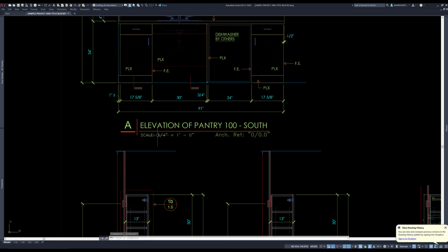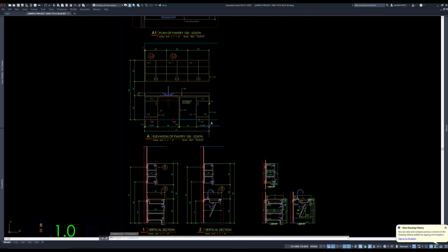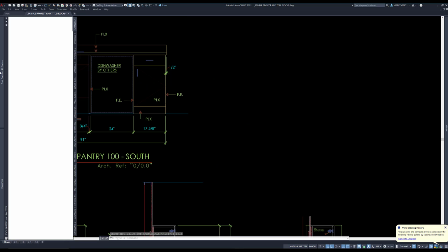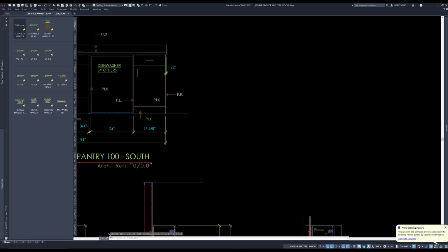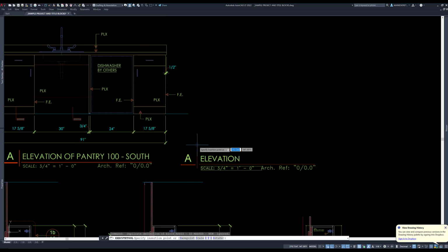And then this here, the scale, is actually set as a visibility, so I can select whatever scale it happens to be in. In this case here, we are 1:1, but the elevation is 1:16. So if I go to 1:16, and I take this and pull it off the elevation, it will be to the correct scale.